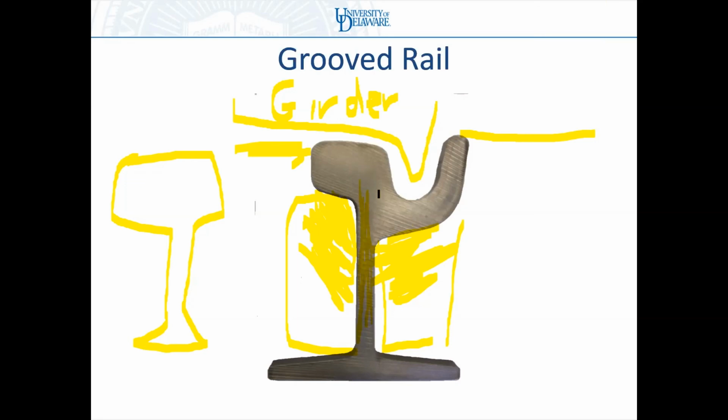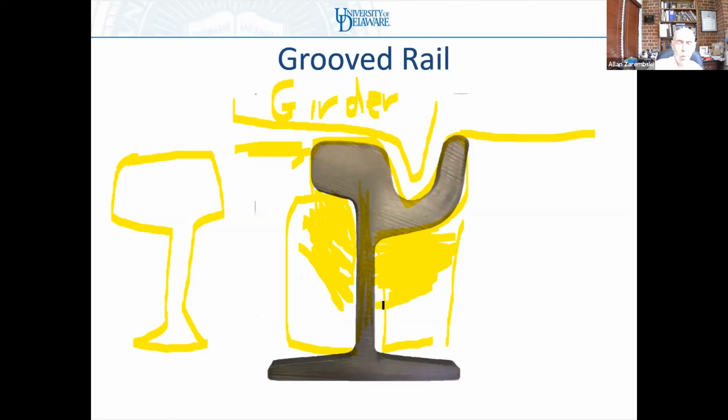I work a lot with grooved rail, but it's not support, as you say, against the twist, because it's all Edilon and insulation and all kinds of material that are very weak. It's weak, but it's dense. We're just looking at providing some overturning moment resistance. We're not supporting the load. We're supporting the overturning moment, which is different.